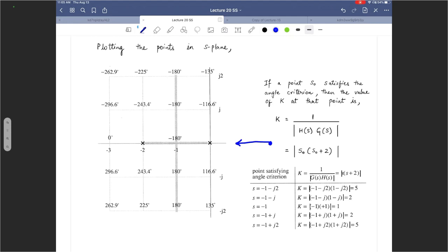And as you started moving left, you simply said no, yes, no. So this means no root locus here, yes root locus here, no root locus here. So you're essentially alternating on the real axis. No, yes, no, yes, no, yes.